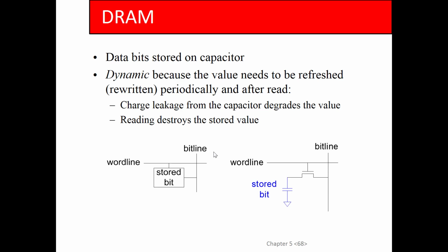capacitor here is kind of strange. When you design digital circuits, capacitance is your enemy, because the more capacitance you have in there, the slower the circuit is. There's this time constant: the resistance times the capacitance is how long it takes you to charge up or discharge a capacitor.